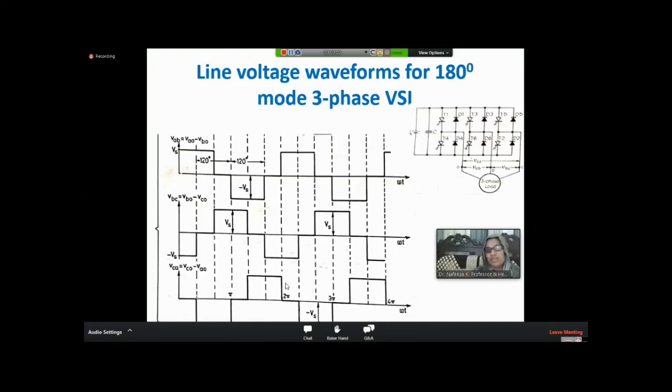Okay. And if you want to double the frequency of this, then what you will do, you will change the switch on time of the switches and let it be 5 milliseconds. If it is 5 milliseconds, the fundamental period becomes 10 milliseconds. So what is it? 100 hertz. So in this way, by varying the switch on period, you can vary the frequency.